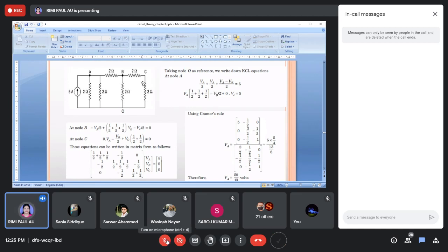There is another method you can use, because sometimes when we see a current source, we cannot understand how to solve the problem. First of all, you can see that the current source is connected in parallel with the resistance. There is nothing else present. So I can convert this source into a voltage source. In some cases you have to convert from voltage source to current source, and current source to voltage source.